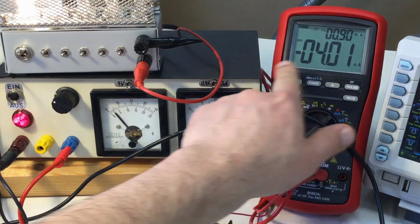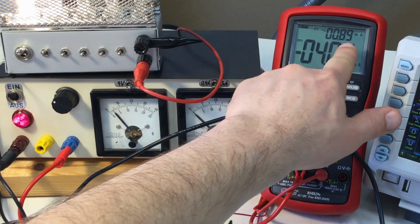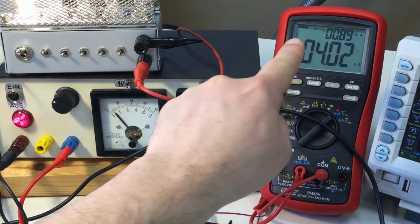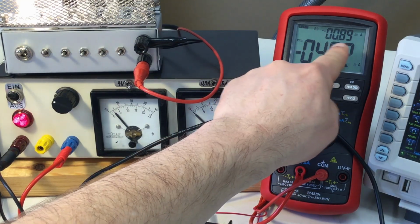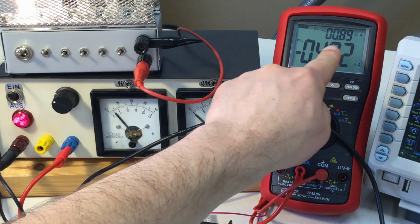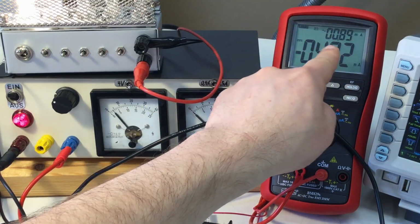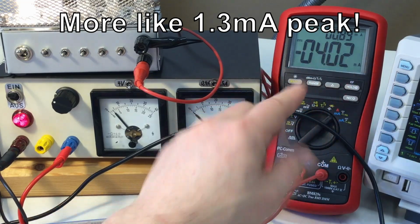So average gate current is about 4 milliamps, but it has an AC component, this little wiggle through the different phases, of 0.9 milliamps RMS. So let's say almost 1.5 milliamps peak.